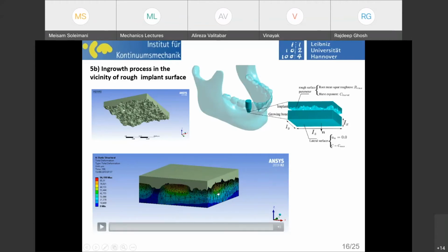You see this super flexibility in order to fill this available space, this very complex available space between those valleys and hills. It is not possible unless you have a very good definition of the growth function, that it is to be isotropic and stress dependent. That means that if the growing body faces some rigid wall, it should have the flexibility to find its way in other directions that are still free. So this sort of smartness or flexibility is basically conferred to this growth model if you use what we explained to be the isotropic growth.